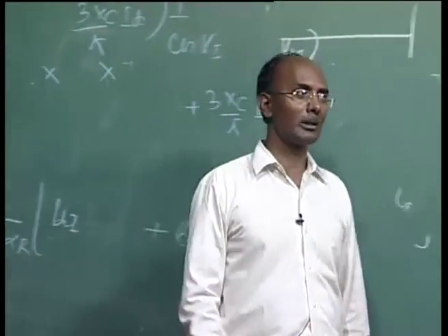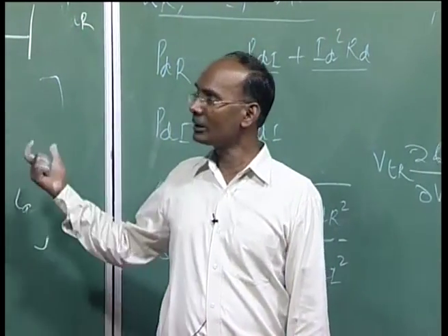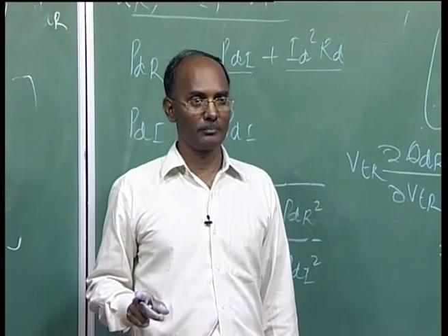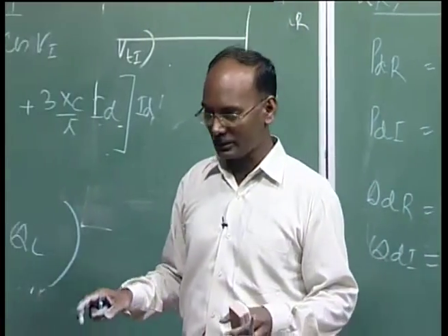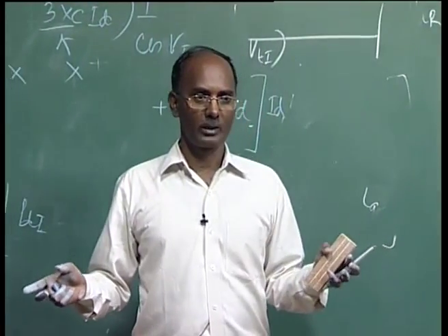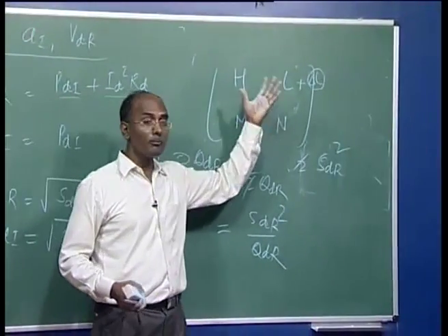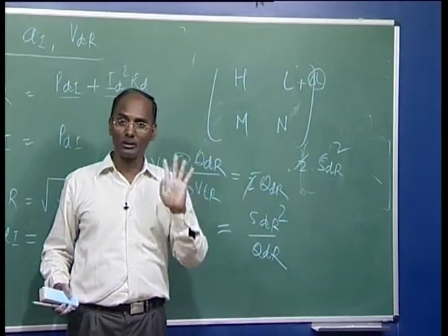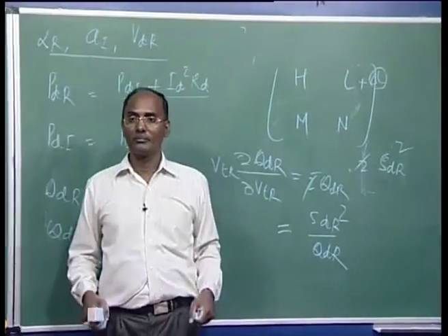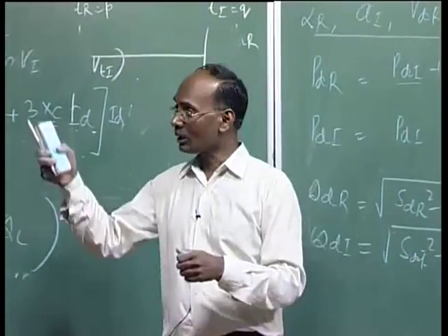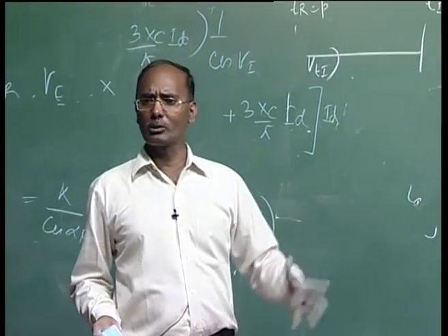So, this is nothing but the extended variable method, and here we discuss the Newton-Raphson method in terms of polar form. It is not possible to have it in rectangular form because it becomes very, very complex. Here it is not our intention to make it complex, and you find it is very, very simple. Sometimes there is no need to modify it, or at maximum we are going to modify only the 8 elements. Depending on the control modes, there is a possibility there is no need to modify. So, very few elements are going to be modified.